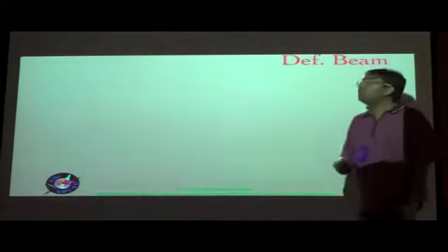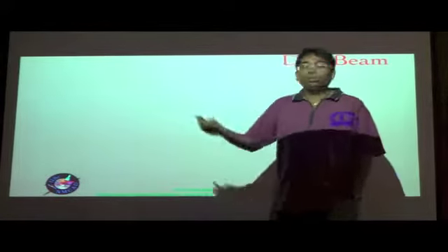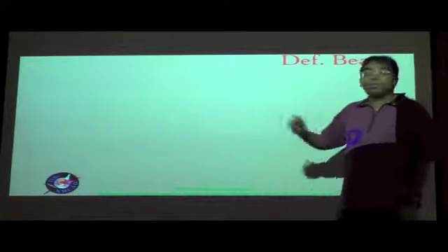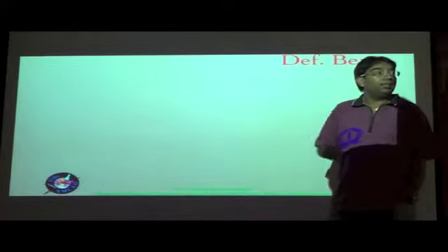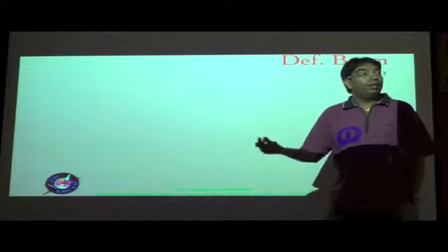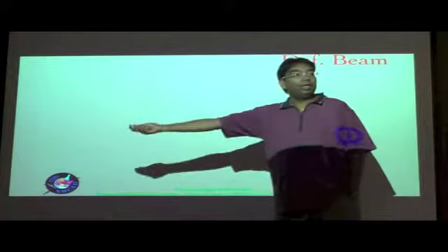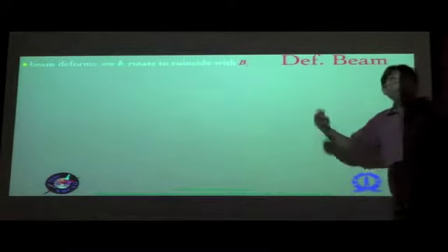So now we will introduce an intermediate reference triad, which is the big T system, T1, T2, T3, in such a way that the T1 is tangential to the reference curve. So it is possible to do the analysis using either B or T. Eventually the 3D fields that you get would be the same, just that one is more convenient than the other depending upon whether you want to lump the transverse shear deformation either in the warping or in the rigid-body-like motions, that is, rotations in particular.